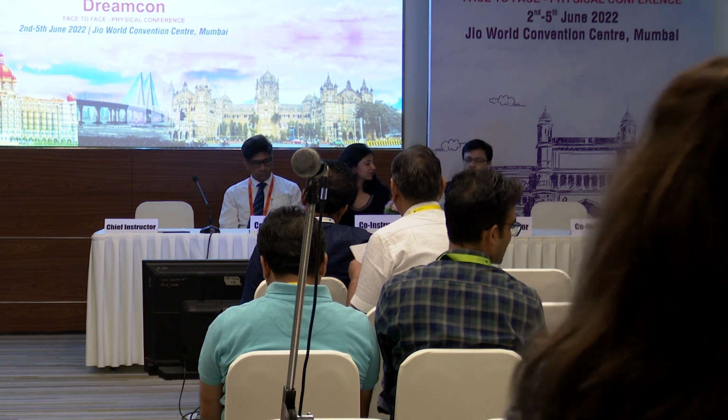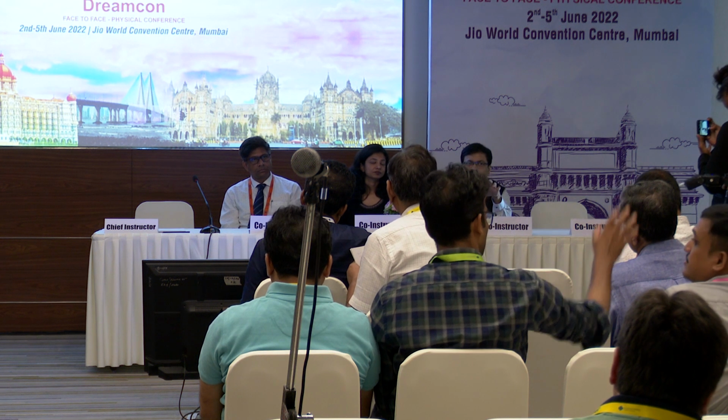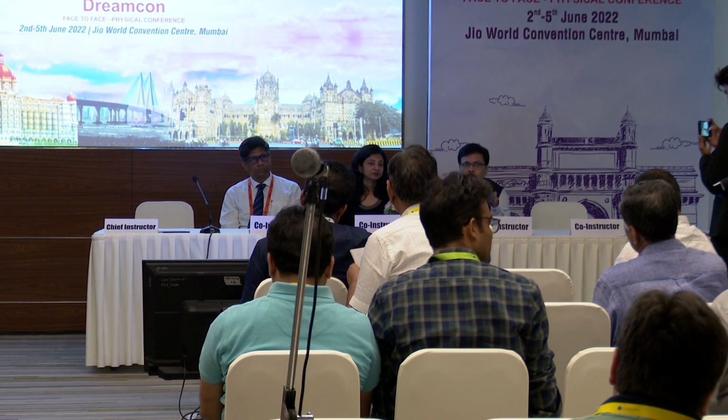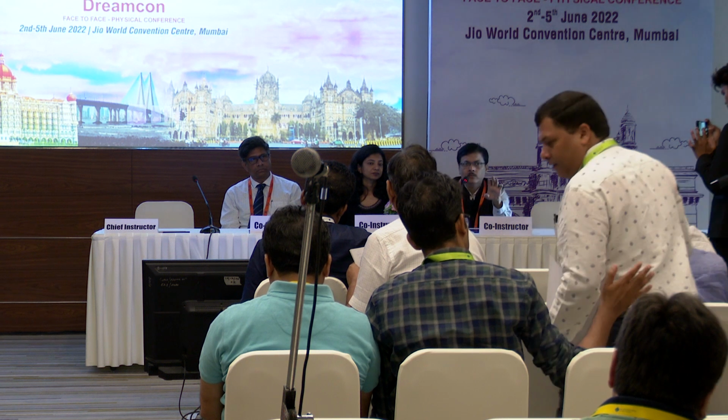Is that NABH? No, I'm not sure regarding that. NABH does not have any such requirement, neither about the size of the OT, nor about the requirement of an air handling unit, nor about a modular or a steel OT. The only NABH requirement is the humidity range and the temperature range as specified, whichever way you attain it.